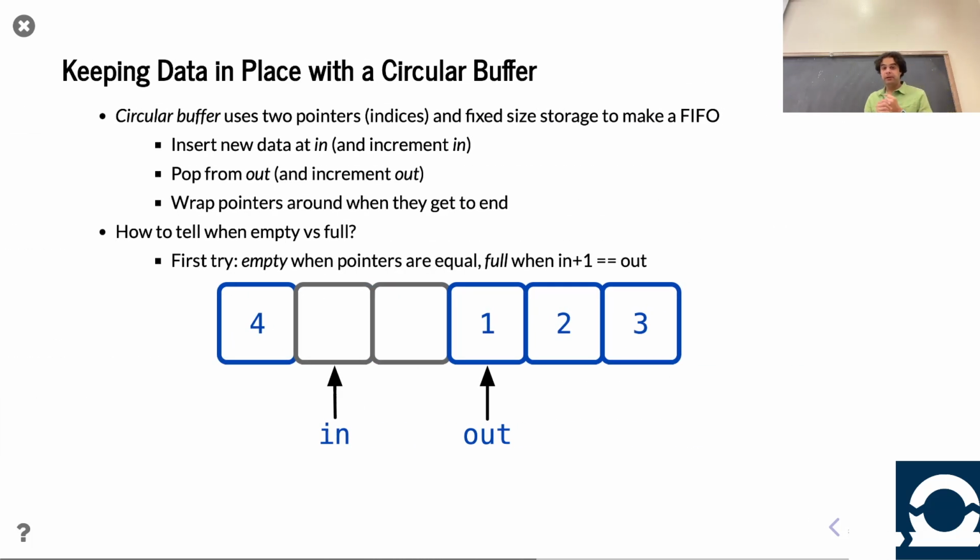Okay, so one idea you might have is, what if instead of having a shift register, rather than moving where I'm moving data, always having a single exit point, what if I can put data into and out of the queue at arbitrary locations, but the data doesn't move, right? In order to save power, we're going to write the data once and leave it there until it leaves. That's the key idea, right? So we're going to change where we insert, where we remove, in other words, where we enqueue, where we dequeue, but data's not going to move. Data comes in once, gets written. It's going to chill until it's time to leave.